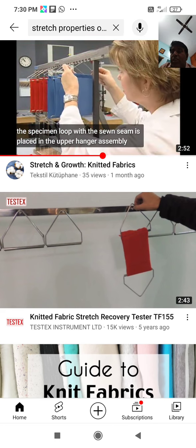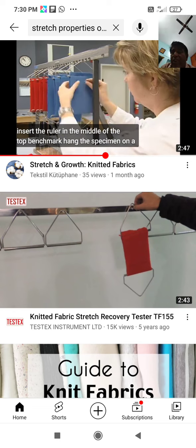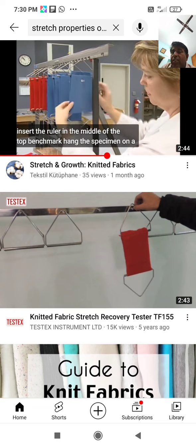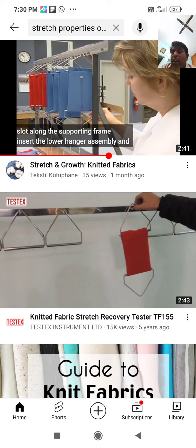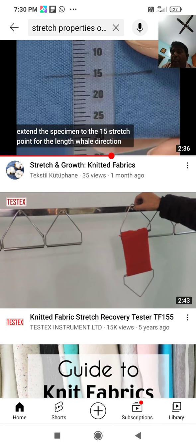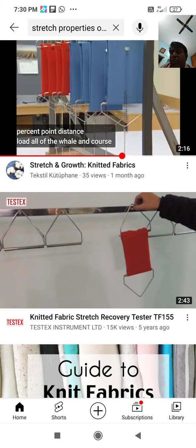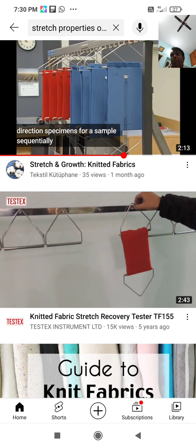To test shrinkage, specimens in each direction of the fabric to be tested are benchmarked for 25 cm in length and width, then dry cleaned or laundered 3 times. Then the specimens are pressed on a flatbed steam press if they were dry cleaned, or pressed with a hand iron if they were laundered. Then the benchmarks are measured and the shrinkage calculated. These specimens are visually evaluated for puckering, delamination, crack marks, or any other surface damage due to dry cleaning or laundering.